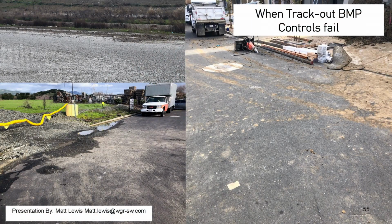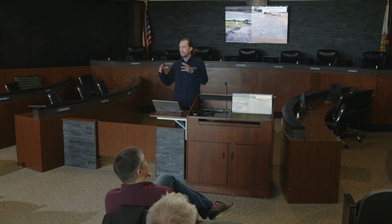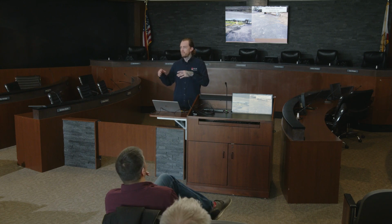You get an excavator in, churn up that rock, and get that track out maintained. And in the middle right, they just literally don't have track out controls. This was actually the site a few ones back that I was talking about, the landscapers removing the perimeter control. This is all the landscapers right here, just on the other side of the street. They've got a little mini excavator and they're tearing up some sidewalk and tracking out like crazy.